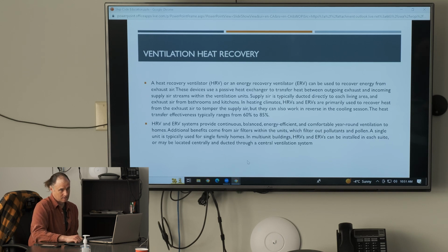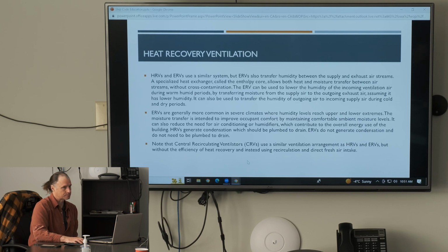That's in terms of efficiency. Yeah, that's just solely the heat recovery ventilator unit. Right. Yeah, that doesn't take into account the other systems, which may be much higher in efficiency. Right, okay. So if you have that HRV connected into your central furnace, it uses that duct system, but that wouldn't change the efficiency at all, would it?